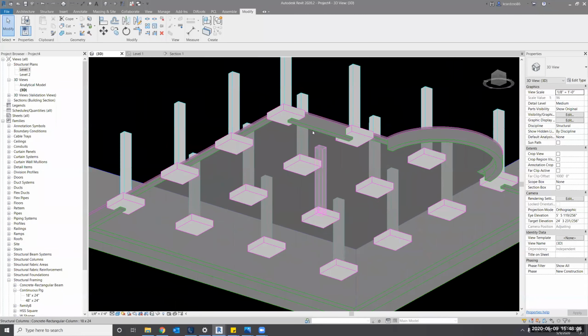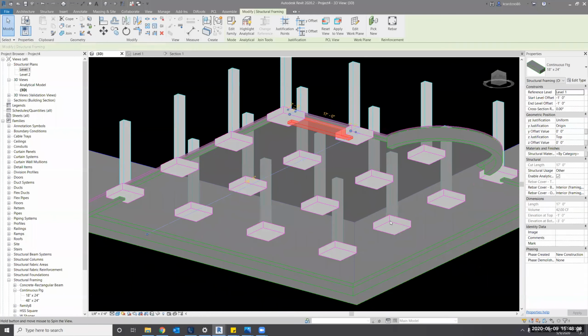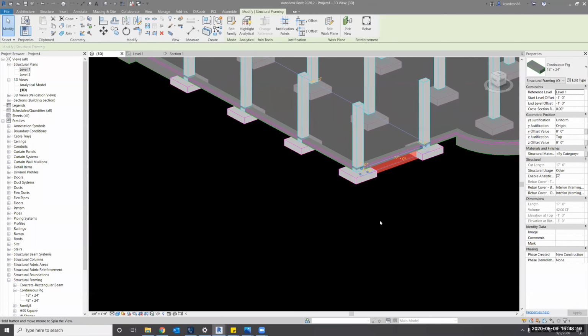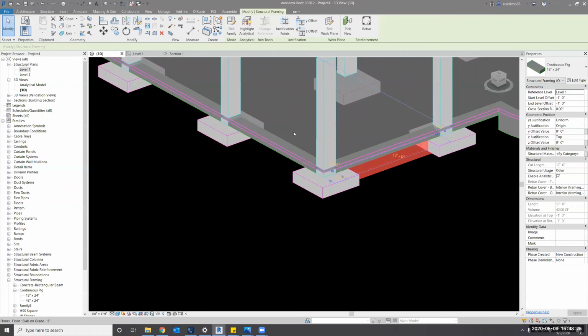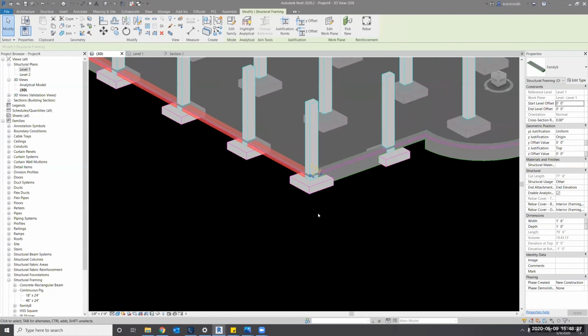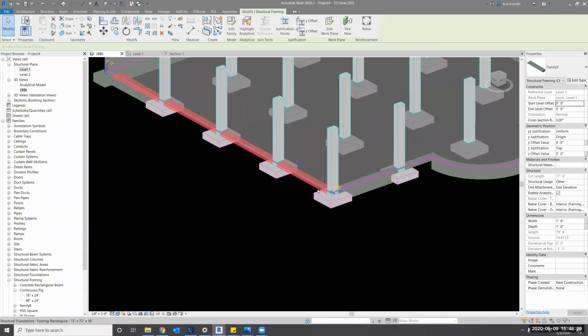So the reason why I'm not going to simply trim everything together is because when it comes to these footings, at least for us, when we work in concrete and we're taking quantities, we like to know the information specific to this footing, right? It was okay to extend this one and make this one element because this is filler. That family is filler, right?